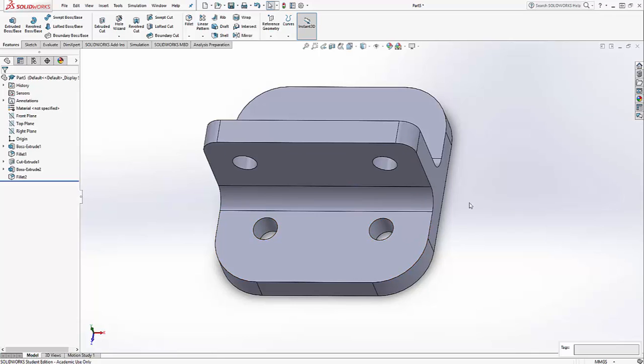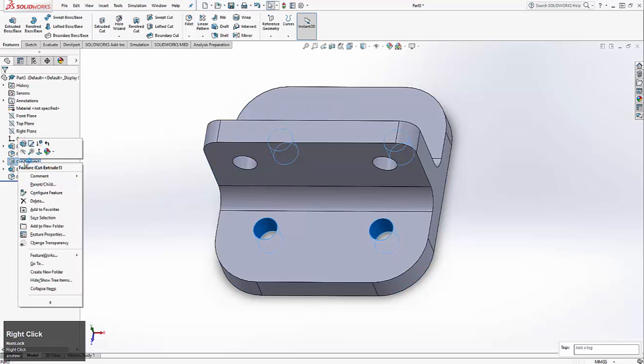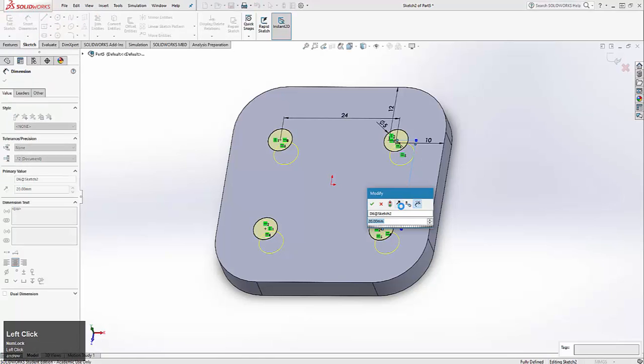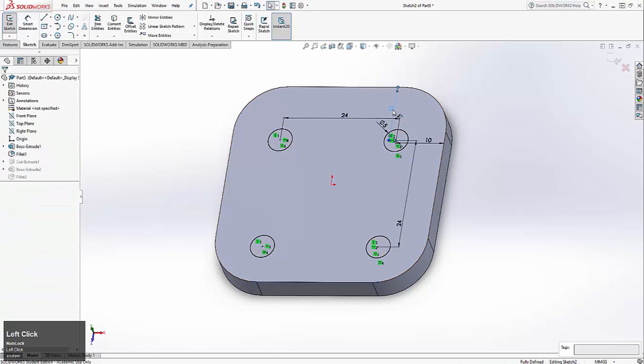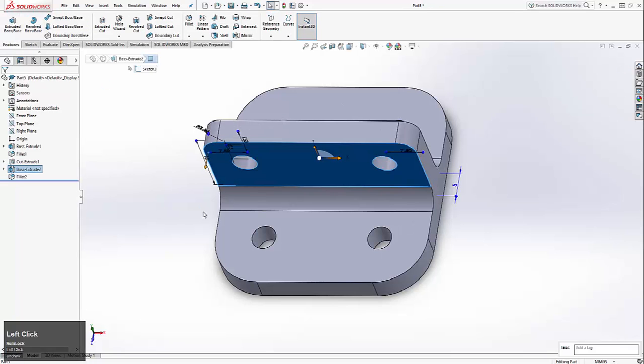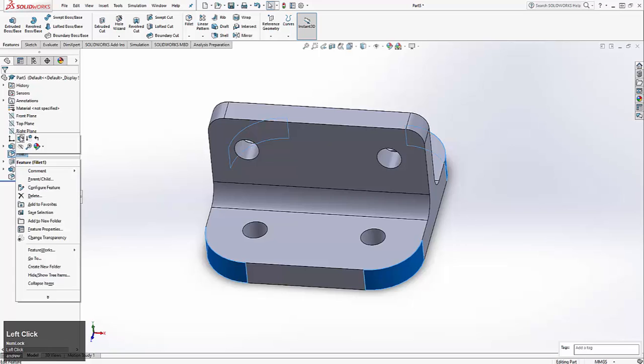So instead of having to redesign your part every single time if it doesn't work, you can use the Smart Dimension and it'll go back very, very simply. So I'm actually going to put it back because it's kind of weird. But feel free to change your part. And then another thing you may notice is, actually first, let me do the fillet. So I also want to change the fillet to 7.5 millimeters.